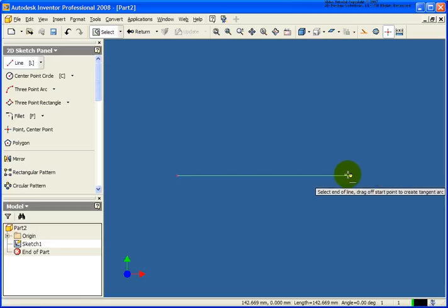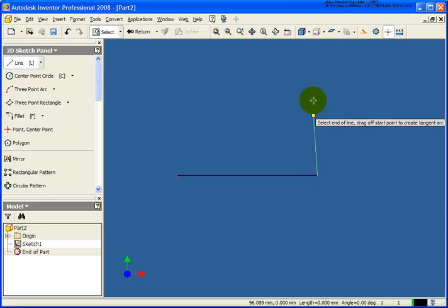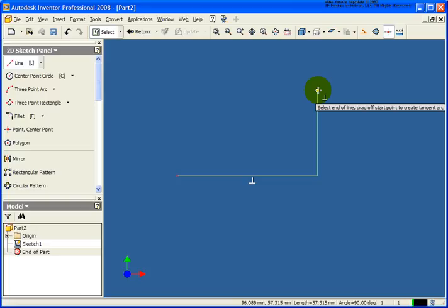Again, that gets me a little bit better position to draw that line right around that 100 millimeters that I was suggesting. Again, this is sketching, so I'm just going to get close. And I can position the line straight up, or in this case, perpendicular. And it's going to go up right around that 58, let's make it about 60 millimeters long.